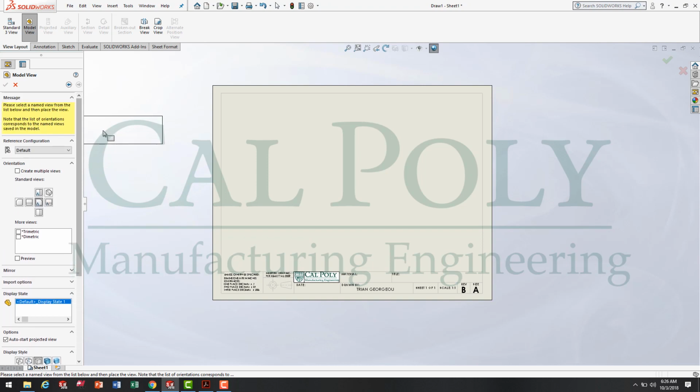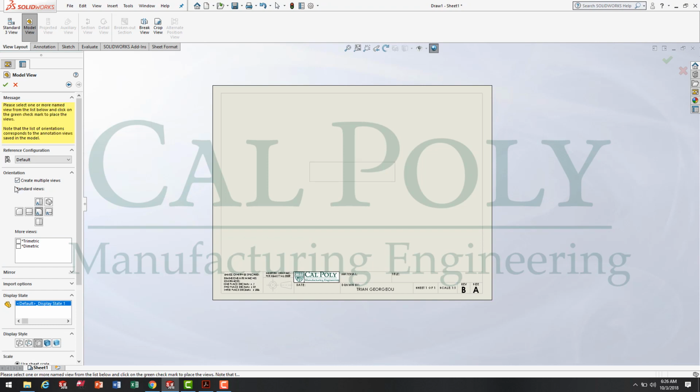So we'll start at the top. I want to create multiple views, so I'm going to select Create Multiple Views checkbox. This allows me then to select my front view as my main view. I'm able to select a right view and a left view, as well as the isometric pictorial view. So those 4 views will be placed on my sheet once I hit the check mark.